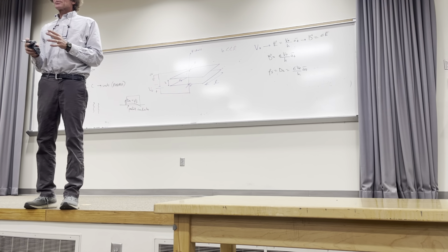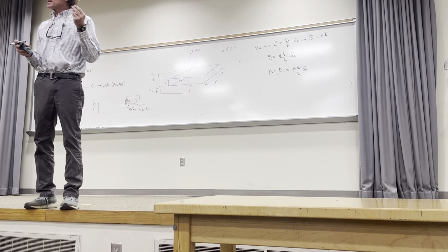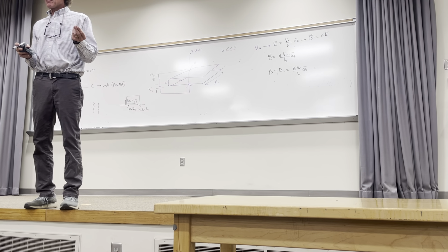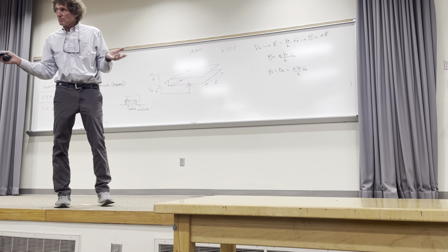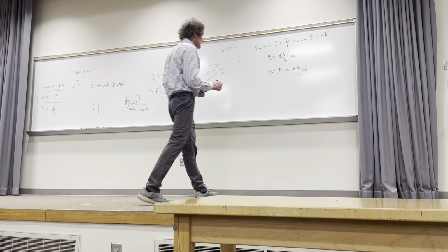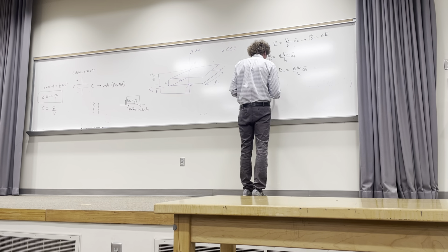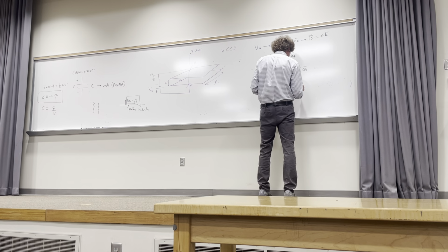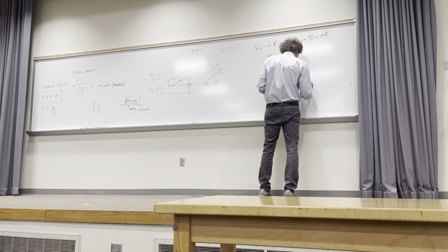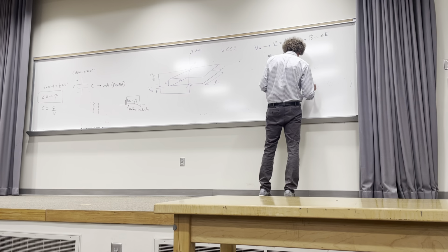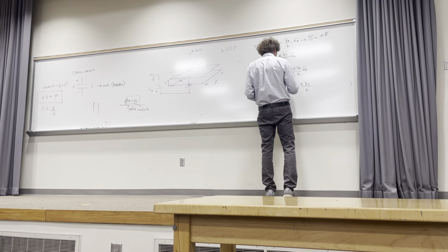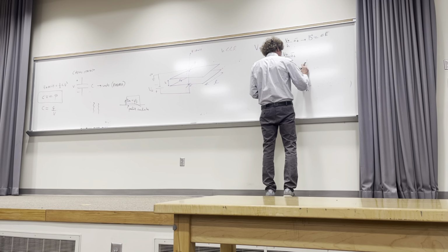But now to get the total charge, what do I do? If I have the density of charge and I want the total amount of charge, standard way is integrate rho s over the surface area, right? But rho s is a constant, so can't I just multiply it by the surface area? Sure. To get Q on one plate, it would be rho s times A. That would be epsilon V naught over H, right there. That's the charge density, and it's just times A, the magnitude of rho s.